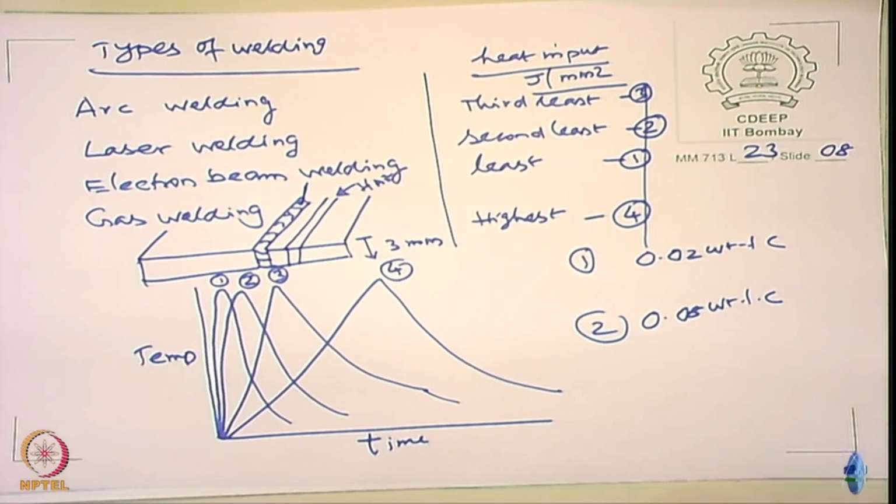Same question that you have been answering: people have found with TIG welding at 0.038% carbon, sometimes there is no weld decay, sometimes there is weld decay. Why? It is manual welding, the person got tired, was not welding very fast, started slowing down the torch. Then what happens? More heat input, got a sensitization problem. So it does not guarantee that no sensitization takes place at all. That is how you need to analyze the problems.